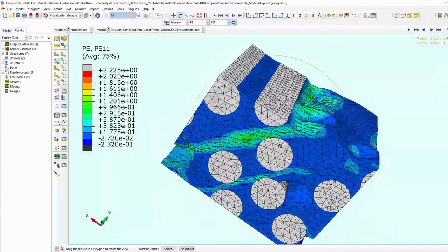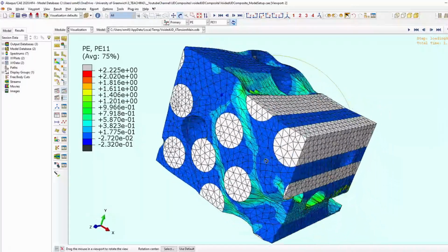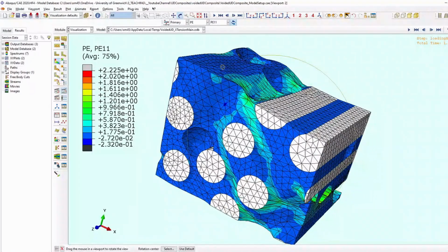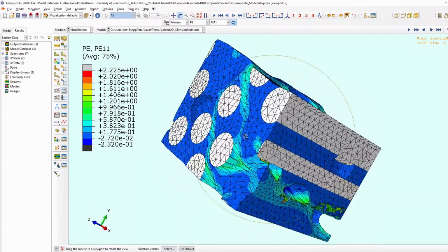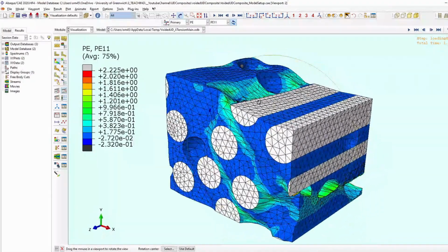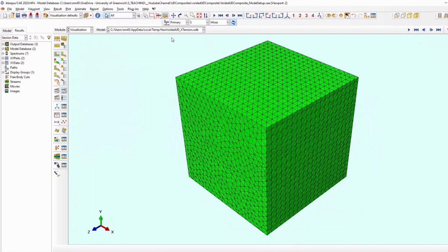So this is a challenge that David will have in trying to use this to generate elastic properties for this composite, because clearly these voids are not contributing in load bearing for this composite, and so it becomes a problem, especially if you think about this edge, where you've got this fiber protruding out. So that's a challenge for David if he's trying to investigate this problem and trying to use this to make some meaningful results.